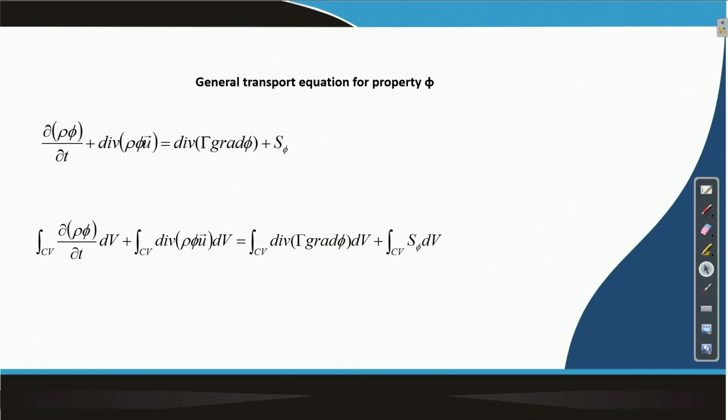So, we briefly looked at the basic framework of discretization, the way we do it for the finite volume technique. In a way, it is similar to finite difference, because we are dividing a certain length scale into subintervals, but then we are not distributing grid points, we are creating control volumes, and the control volumes are set side by side facing common faces, or rather sharing common faces.